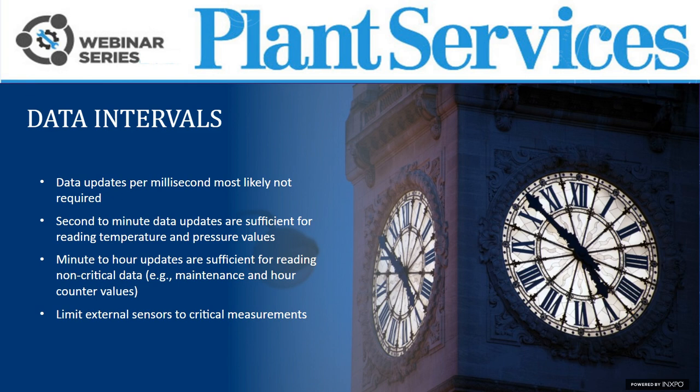So now here we look at some data intervals. Data updates per millisecond are most likely not required in the compressed air system industry, contrary to some mission critical applications. Second to minute updates are sufficient for compressor critical data, and minute to hour updates are sufficient for compressor non-critical data. Again, both very important data points. I also like to highlight that more sensors are not always better and don't add any extra benefit to an operator.